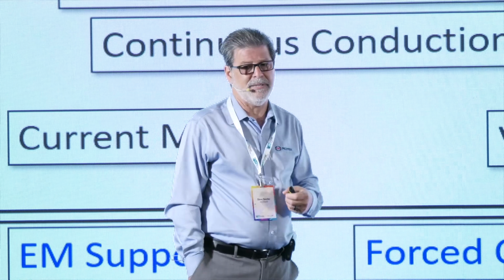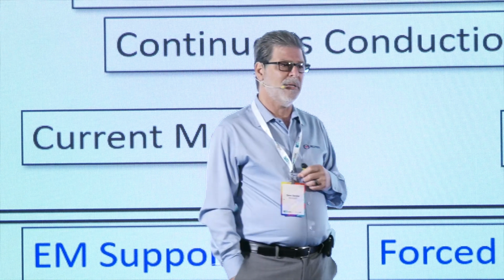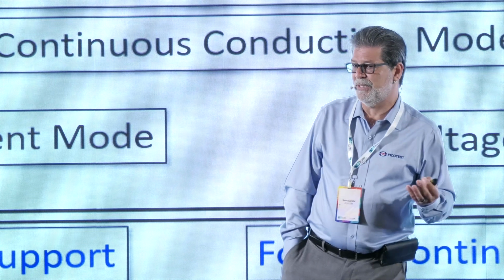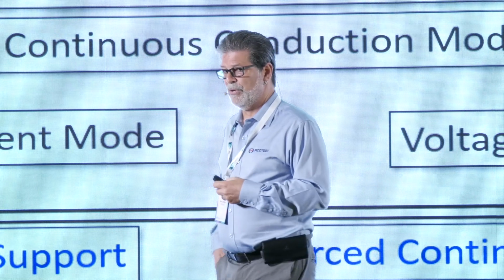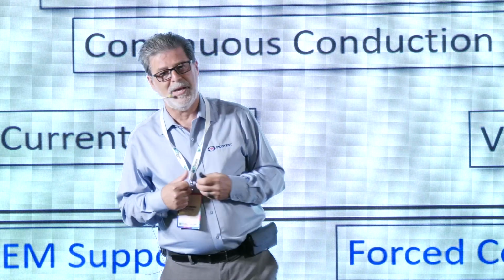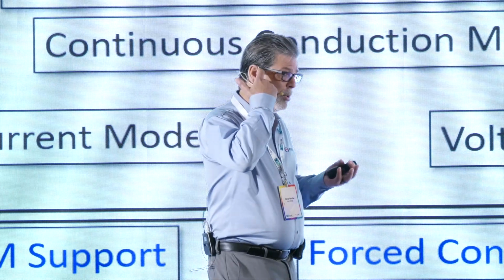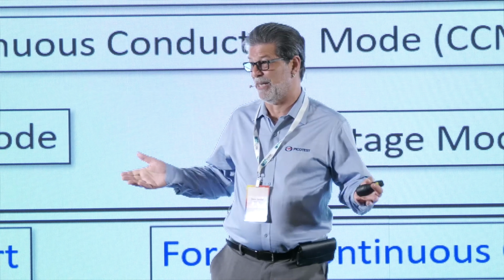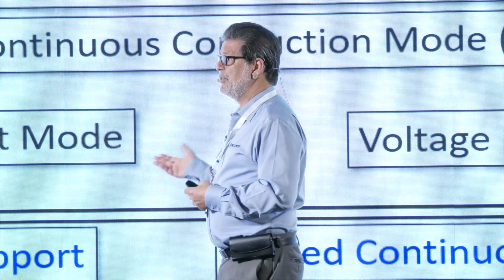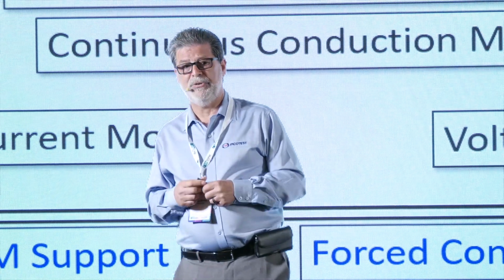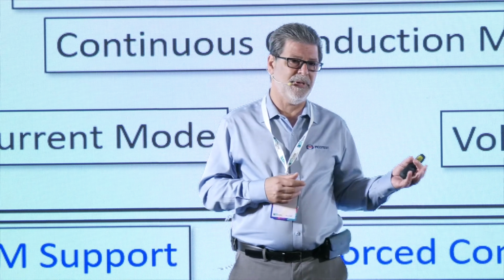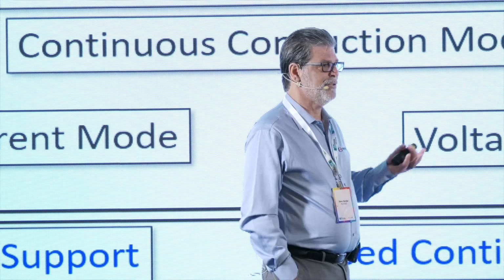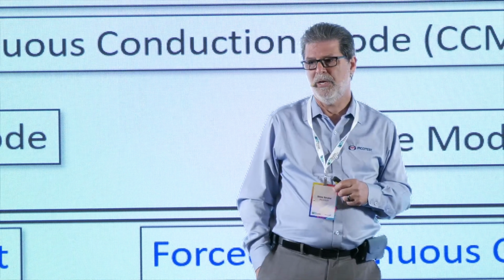In 2017, I made the next major advance in my VRM model, and that was to move the entire simulation model to a harmonic balance engine. Harmonic balance is a native Fourier simulator. There are no voltage equations or current equations. That makes it much, much faster. In a power world, it also gives us a couple of major advantages. One is that the actual answer is a spectral response, and that means that it's really well adapted to EM simulation. It's capable of doing things like EMI simulation, and of course we can reconstruct IFFTs, and using IFFTs we can recreate time domain measurements.